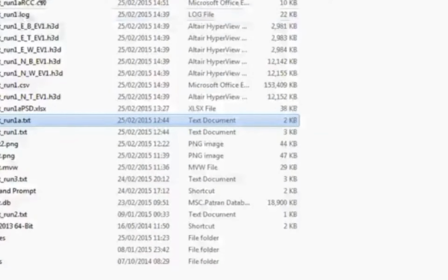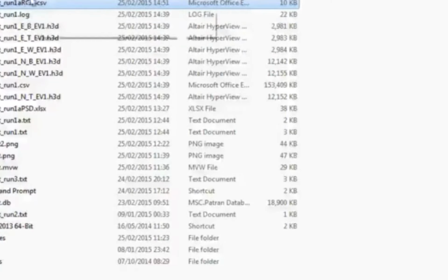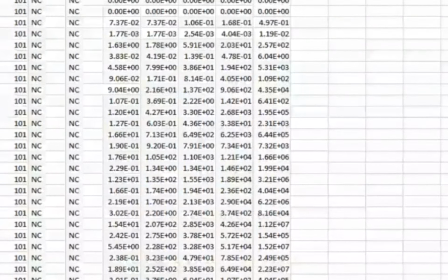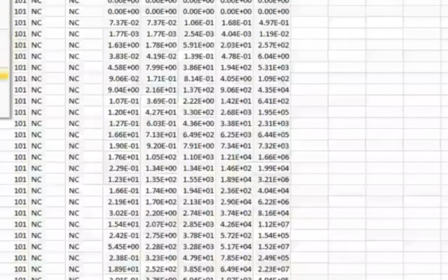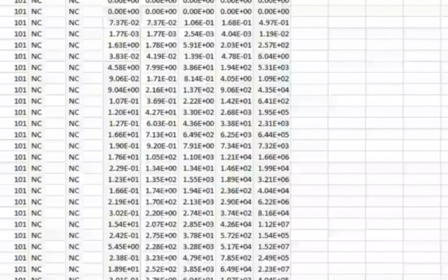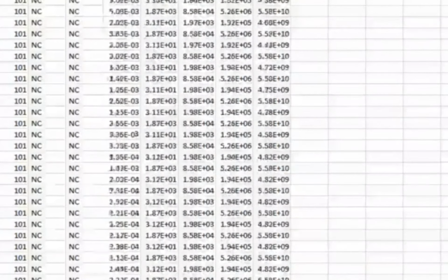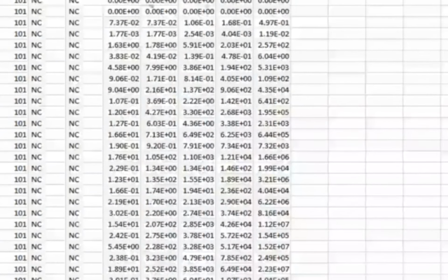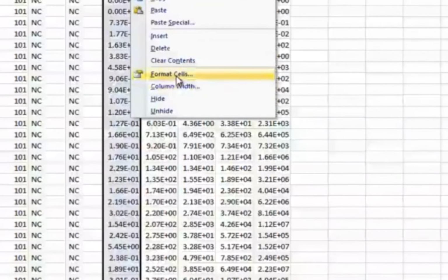So it's written a couple of extra files here, one called PSD.csv and one called RCC.csv. The RCC has the rainflow count data in it. I'm not going to look at that, but I'm going to look at the PSD file. If I open that up, it gives me only for this one element, 40631, the response PSD information at different frequencies, going from 0 up to, what's the maximum in here? 500. So from 0 to 490, I've generated a PSD result shown in column H.